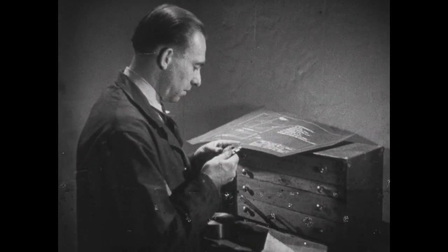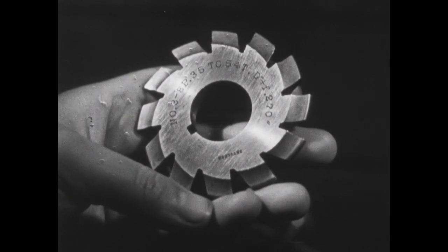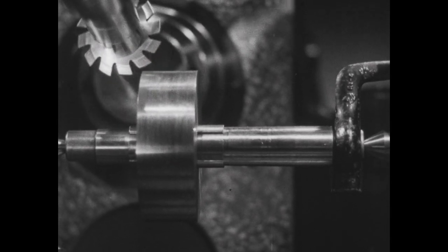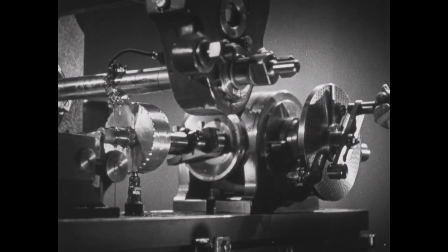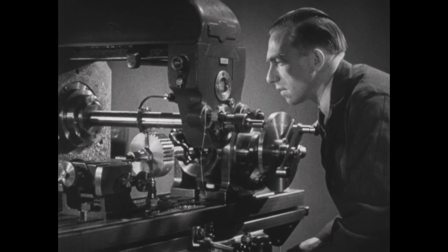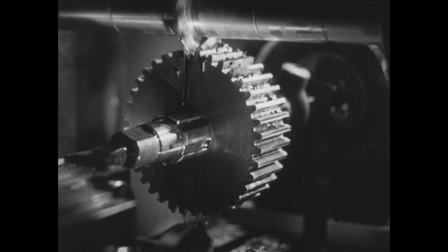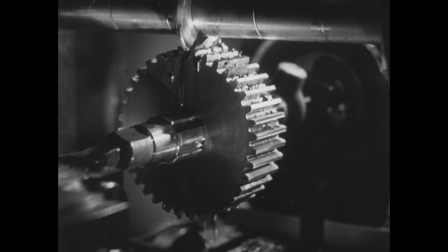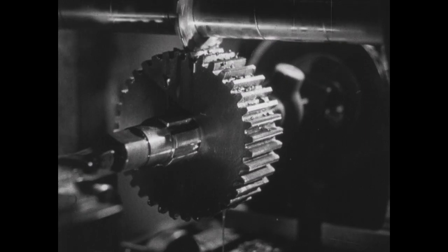For if the proper cutter is selected, a cutter stamped with the specifications called for on the blueprint, if both the work and the cutter assembly are rigidly set up, if the location of each cut has been accurately calculated with the dividing head, if the proper speed and feed have been set, and if the entire setup has been carefully checked before making a single cut, then the last step, actually producing the work called for, is a relatively simple procedure. And the result is a spur gear cut exactly to specifications.